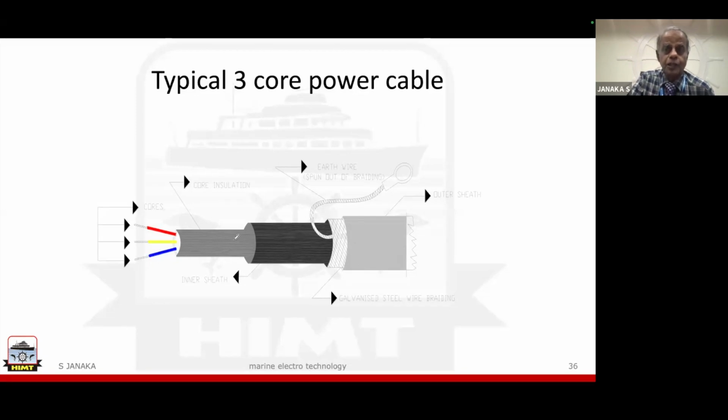So it is posing a continuous risk that whenever the current is flowing continuously, there will be static charges in the cable. To eliminate them, on the upper layer we have got something called a metallic braiding or armoring provided. This armoring, you see that lug with that material, that same thing like a braiding material, through a lug, it is connected to the ground.